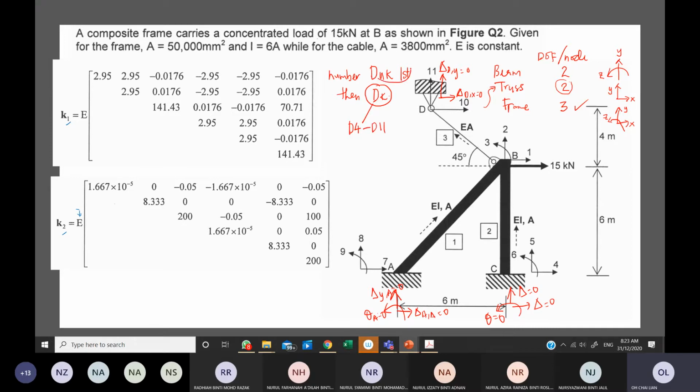And these are the unknowns, the remaining ones, which will be at B. There is no support constraining this displacement, meaning that at B, this point can move horizontally, vertically, and also in rotation. So this D1, D2, D3 has been given the value, followed by the known displacements. I hope you understand this.